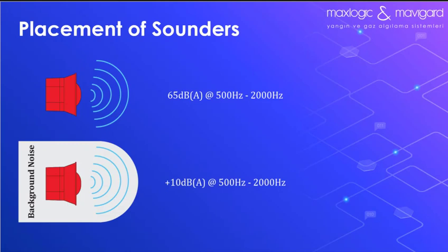After the change of 6.6.2 audible alarms, the sound level provided should be such that the fire alarm signal can be heard just above any ambient noise, but the sound level should not be above 118 decibels at any point where people may be present. The fire sound must continue for more than 30 seconds, at least 65 decibels or 10 decibels above any noise, whichever is greater.